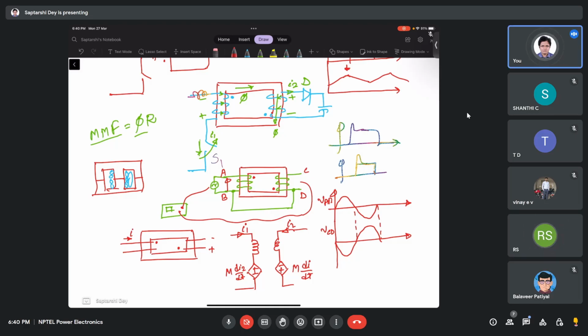And to make things simple in DC-DC converters, I told you that since V equals L di/dt, di/dt positive means V positive, so increasing current means positive voltage. So if I have the dot positive in one winding, it will be dot positive in all other windings.